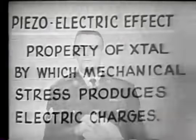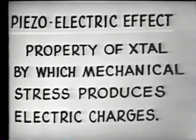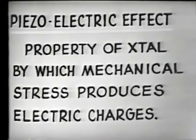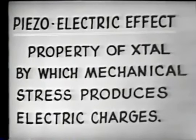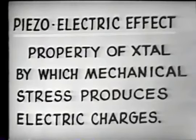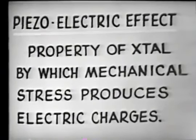An overtone crystal. Now, let's recap a few of the points that we've discussed in this lesson. First, we saw the use of the crystal. Now, we said that the crystal must exhibit the piezoelectric effect. And we define the piezoelectric effect as the property of a crystal by which mechanical stress produces electric charges, and conversely by which electric charges produce mechanical stresses.